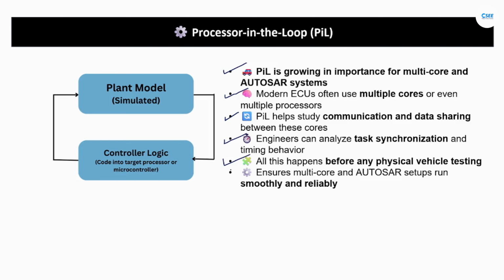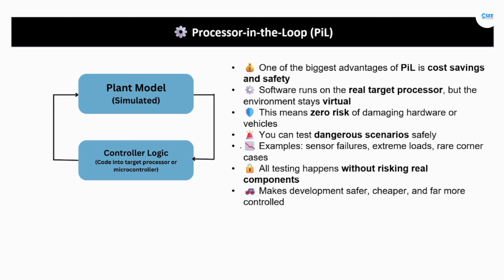Finally, one of the biggest advantages of PiL is cost saving and safety. Running the software on the target processor while keeping the environment virtual means no risk of damaging hardware or vehicles. You can test dangerous scenarios, sensor failures, extreme loads, or corner cases completely safely without putting real components at risk.